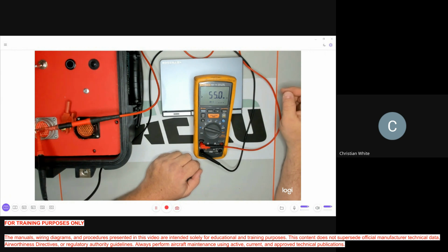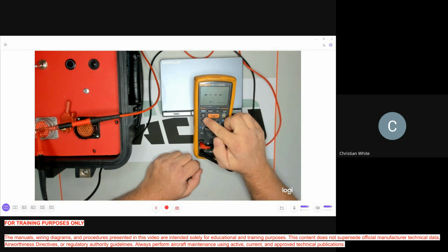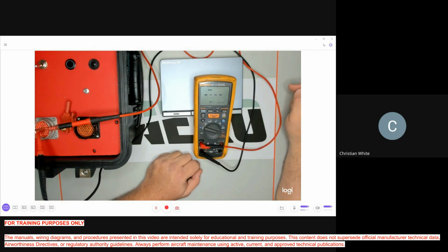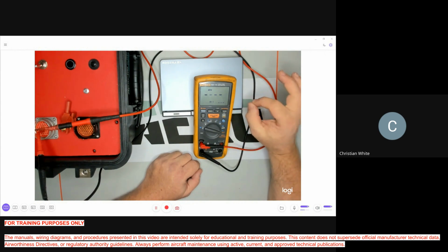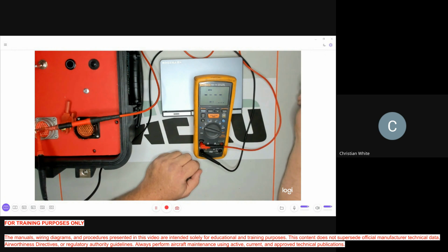Our normal process now is, instead of just holding the button, we're going to use this here. We're going to select either PI or DAR. They are basically the same thing. DAR does a test for a minute. So if I push that button, it's going to run through that test for a minute, or until it sees a stable reading that does not fault. It's called a dielectric absorption ratio test. That's what DAR stands for. It's really going to take the first 30 seconds, put it over the second 30 seconds, and give you a reading. We don't need to really worry about that DAR reading.